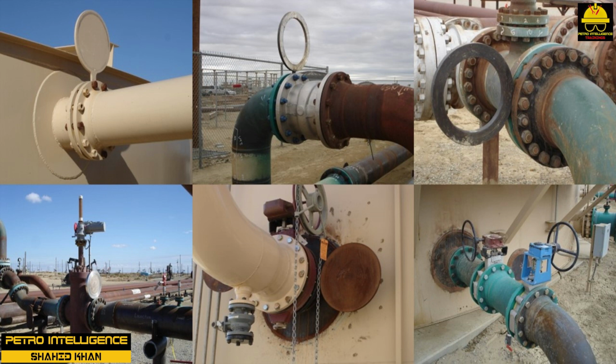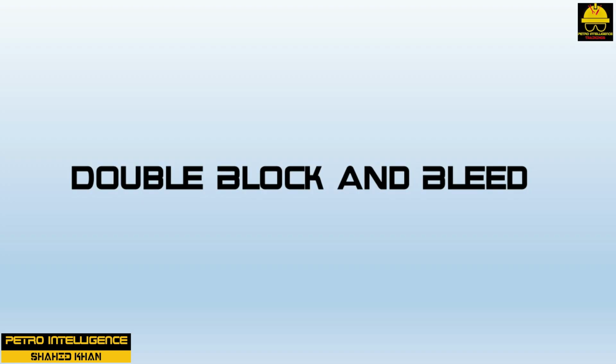The second type of blind, the figure-8 blind, is designed to be installed inside the piping. On one end of the blind is an opening to be used as a spacer between 2 flanges when the blind portion is not in use. The figure-8 blind has an advantage in that it is always at the location of use, whereas the paddle blind, when not in use, can be misplaced.